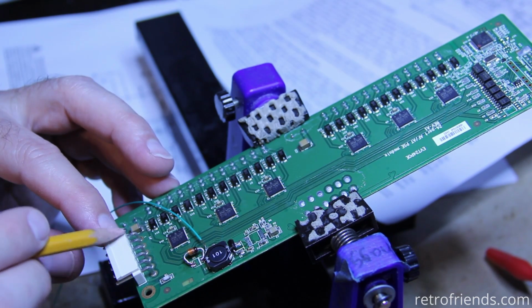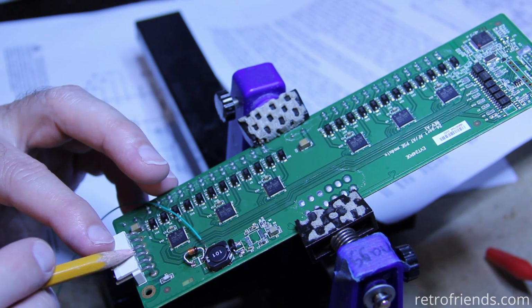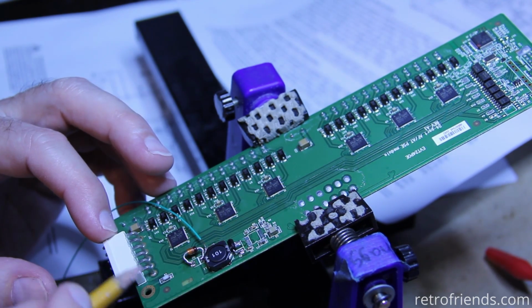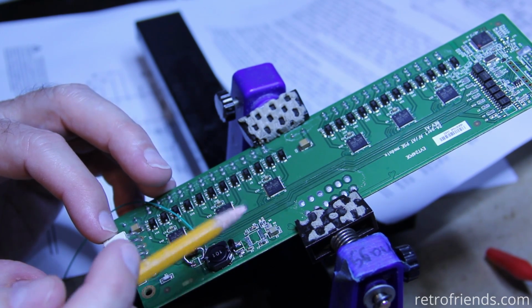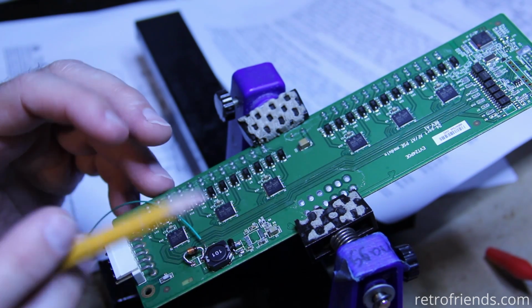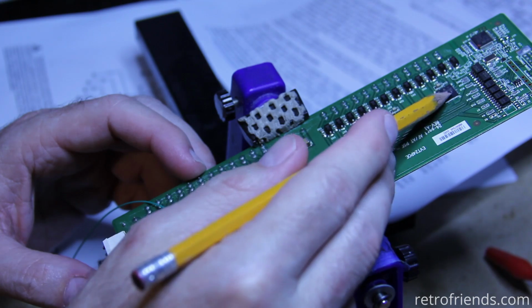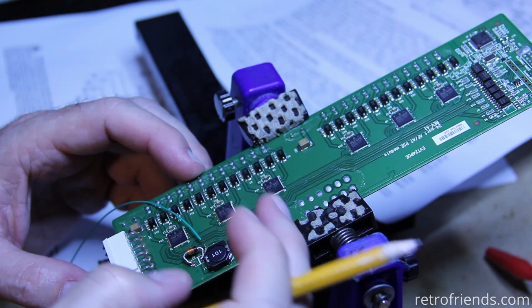And so these first 3 pins are the negative signal for the PoE, and these other 3 are the 56 plus volts. The reason why it's 56 instead of 48 is that PoE uses diodes here, and when you use a diode it drops the voltage a little bit. These 6 chips all need 5 volts of power, and guess where it comes from? It comes from this little circuit here.